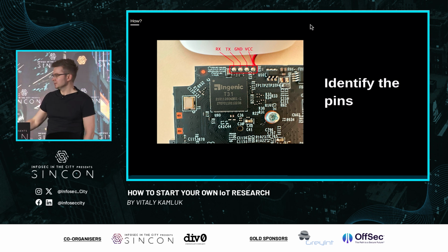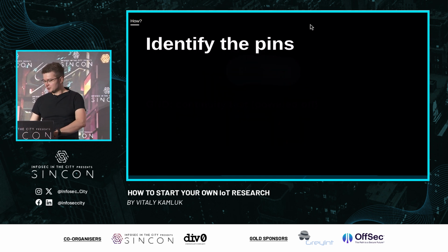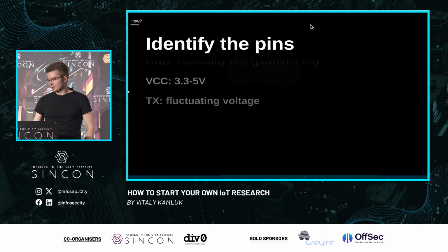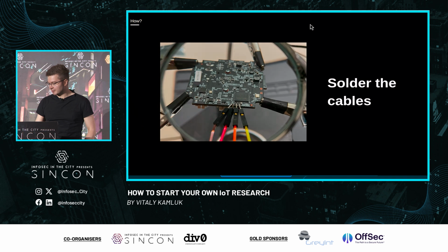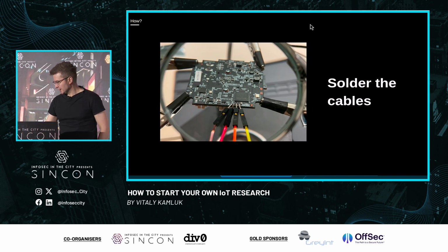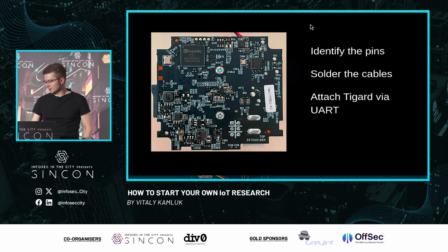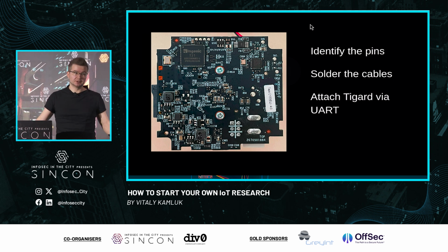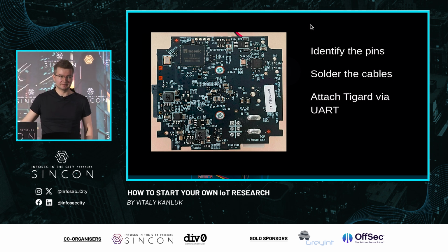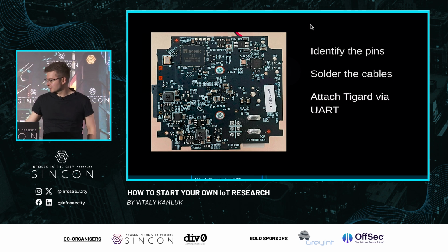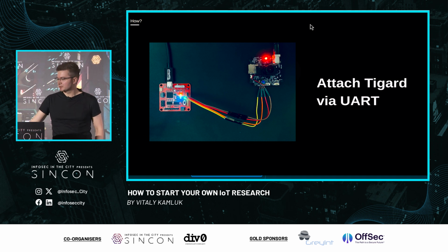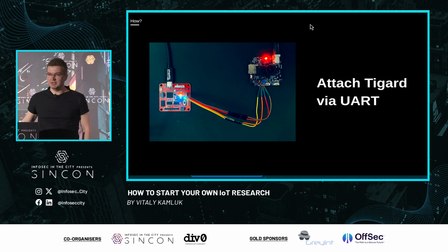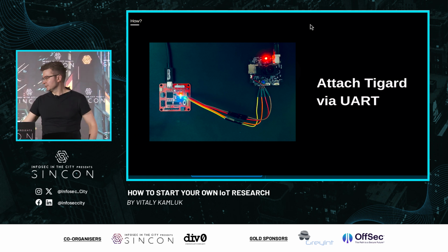And now that you have deduced the scheme, you can use that to connect the cables to these pins. You have to solder them carefully. That's what I did. And then these 4 cables will be attached back to the Tigard. Again, it's not only useful for dumping memory from the chips, but also to interact with UART. So there's an interface for UART. And then the USB-C cable goes into the laptop, you start a terminal application such as Minicom, and then you basically get a terminal, a console of the device itself.